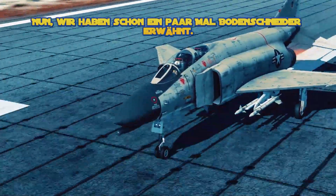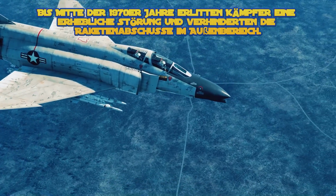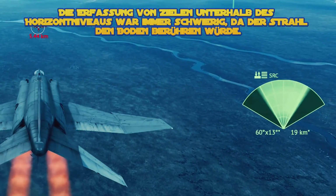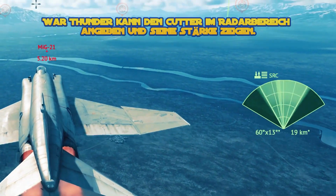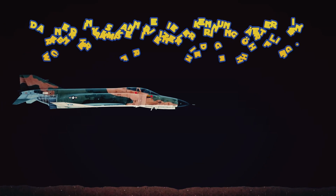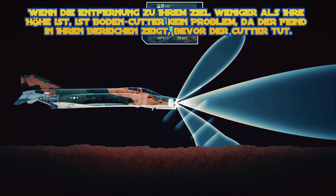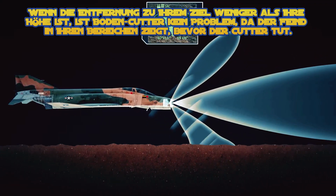Now, we've mentioned ground clutter a few times already. Up until the mid-1970s, fighters suffered significant interference from it, preventing beyond visual range missile launches. Detecting targets below the horizon level has always been difficult because the beam would touch the ground. War Thunder can indicate the clutter in radar scope and show its strength level. In addition to that, target detection may be harder if the fighter flies at a low altitude. It happens due to the radar's side lobes emitting and receiving reflected signals. If the distance to your target is less than your altitude, ground clutter isn't a problem, since the enemy shows up in your scopes before the clutter does.